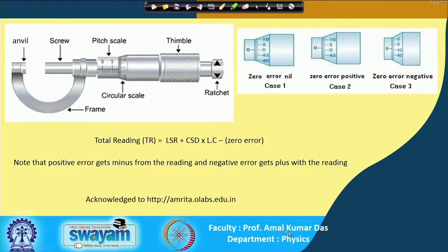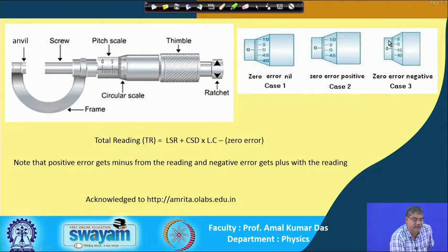So, in the screw gauge, about zero error. In this case it is a negative zero error, because it just crosses the zero of the linear scale, right. I was taking the reading where this 45 or 46 coincides with the linear scale zero, but that is not correct. Actually, this zero of the circular scale, where is it with respect to the linear scale.